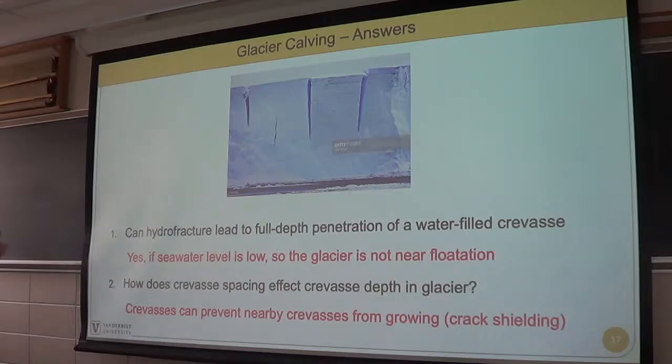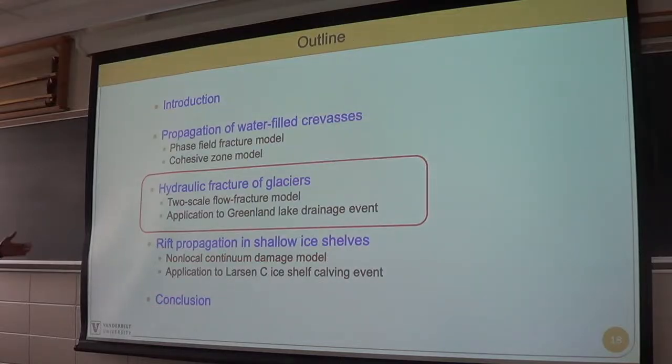Okay, so now moving on to the next bit, we change from a phase field approach to a cohesive zone model approach. We do that precisely because phase field is not yet fully developed to handle fluid flow. So in our previous model, we have standing water. We assume that the fracture propagates, some more water goes in, there's no flow, it's quasi-static, and the water level is changing.